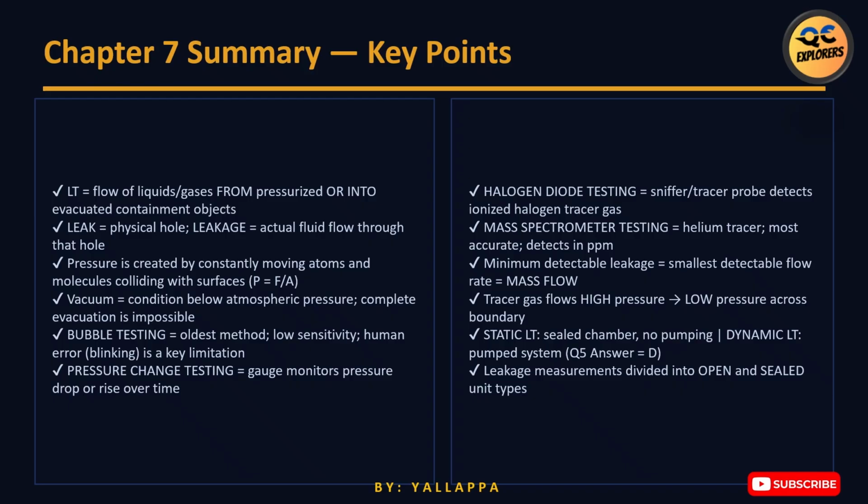Bubble testing. Pressure change testing. Halogen diode testing. Mass spectrometer testing. Each method has advantages and limitations. Technique selection depends on application requirements. Not just sensitivity. This is a very important level 3 concept.